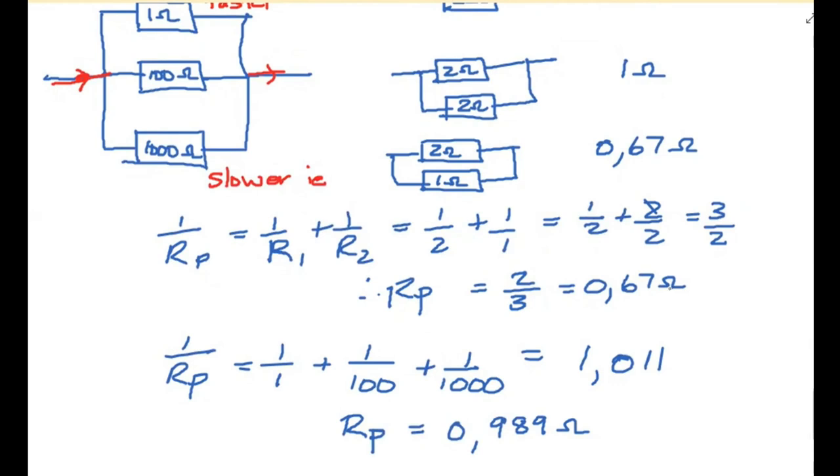So in terms of Storm's question, Storm, you might have learned series and parallel equations that your schools taught you to memorize. Would you like to just share the exact formulas you're talking about? I think that you're speaking about voltage divider, for example. Yes, so I am. So what formula did your school teach you? So for potential difference for voltage in series, they said if you cannot calculate the voltage, you can plug it into a voltage divider formula, which says V2 ohms is equal to R2 ohms over R total times by V total.